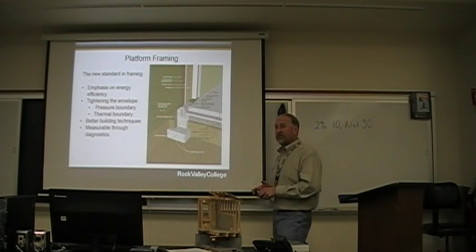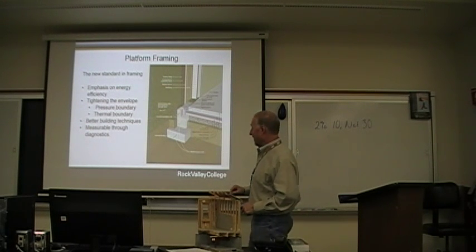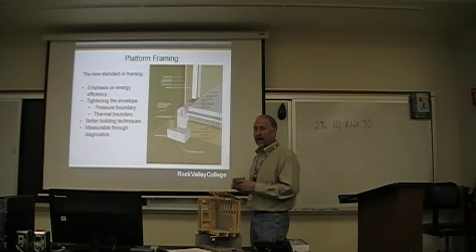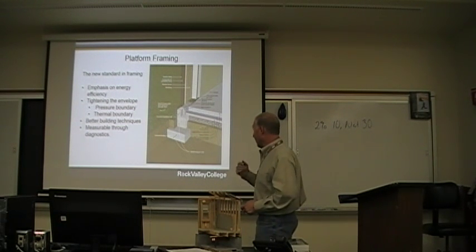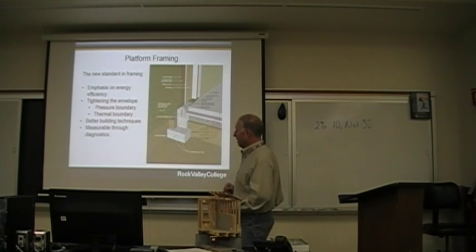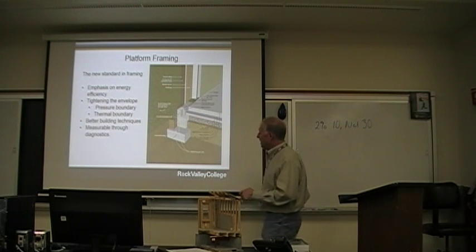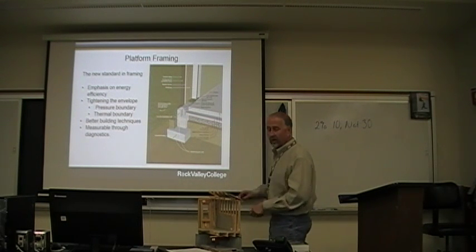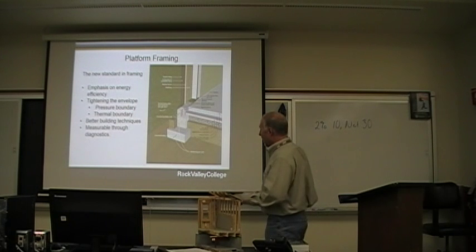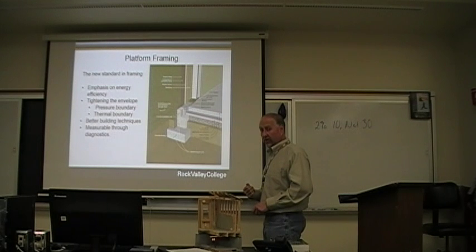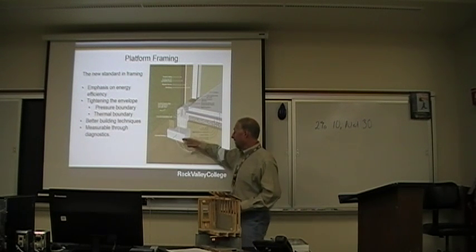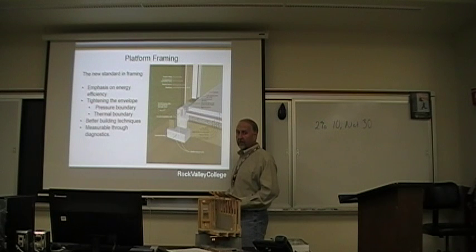We talk about this in the home performance section. Okay, we're going to talk about how we make those align and what we have to do to make them work together. We're talking more about our framing right now, our platform framing. So we're also looking at using better building techniques. As you can see here, we have somewhat of a foundation. In North Carolina, our frost line is 12 inches. So the International Residential Building Code says that our footing has to be down at least 12 inches in grade in order to meet code.